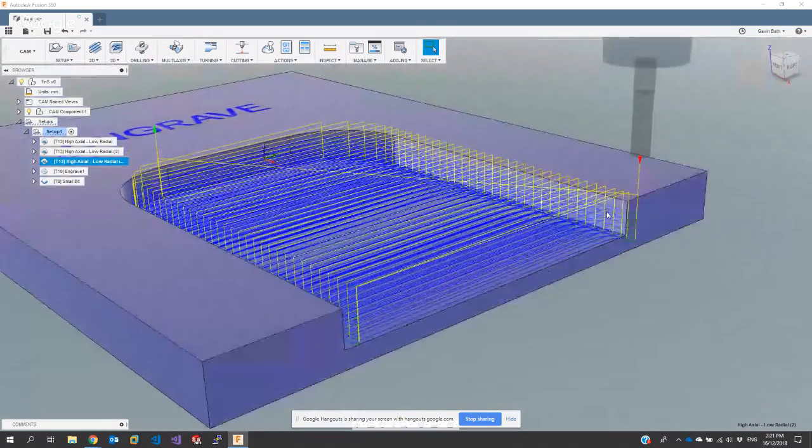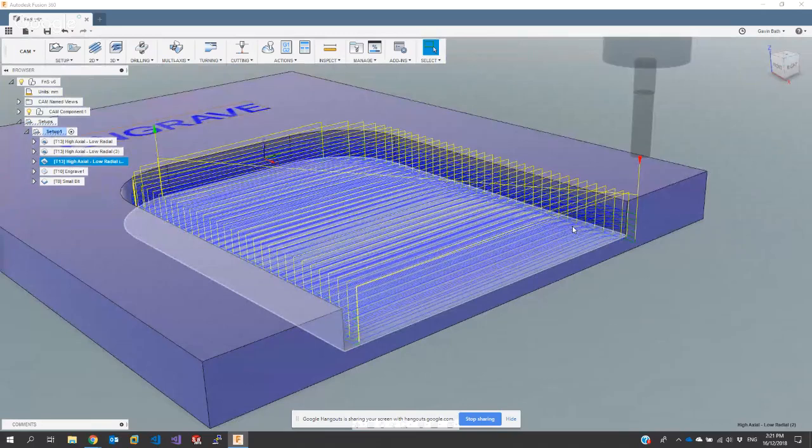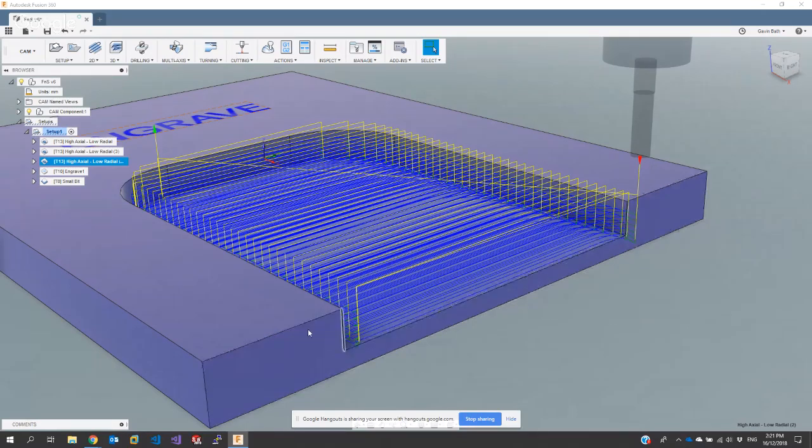So we tend to find, most of the time in something like plywood, MDF, I do a bit with bamboo ply, I'm usually not taking more than 2 or 3 mil depth of cut, but I'll be using maybe 80% of the diameter of the tool and going at 1500 to 2000 millimeters a minute. So that tends to be the formula that will work for me, and we'll come back to those numbers in a minute. But maybe if you could just share some of your views on what's been working well for you guys with your machines.